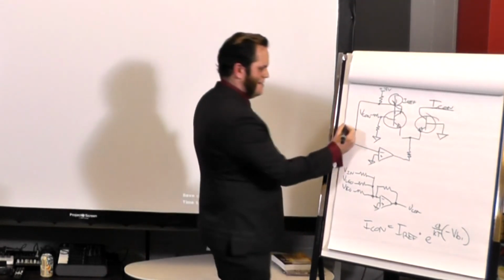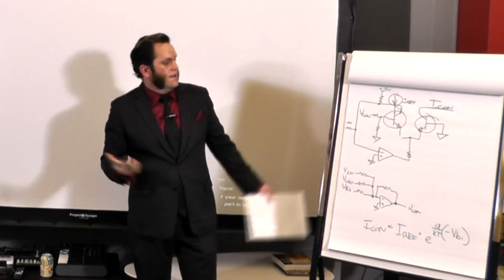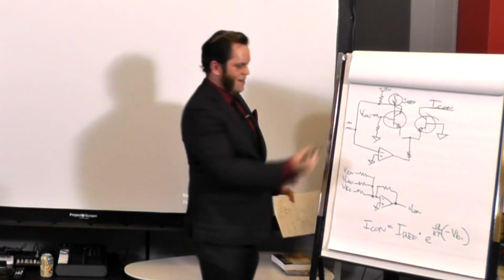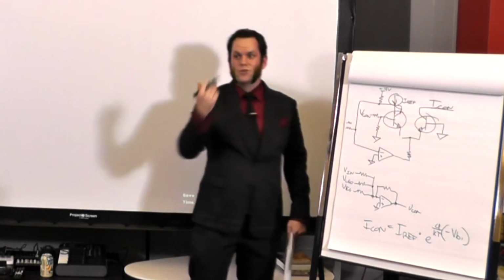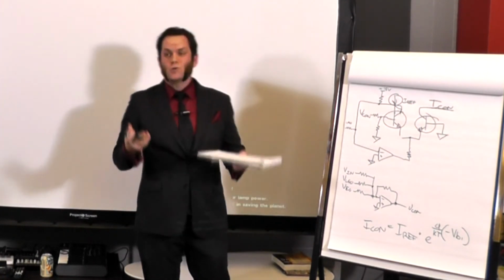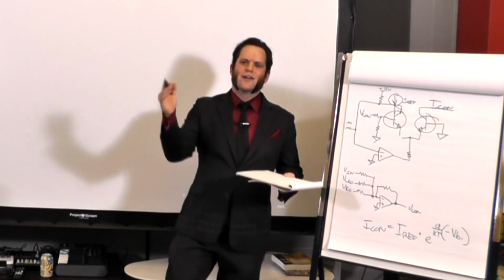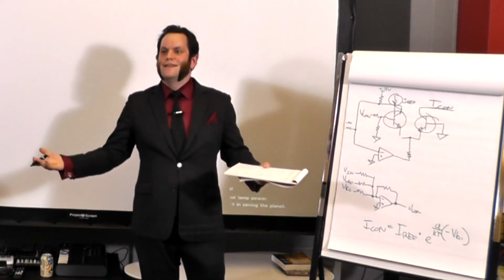So if I want a linear LFO to wobble my frequency, I can just throw that in there, and now I'm getting linear current changes for linear voltage ins. Depending on how you wire this guy up, you can get all sorts of fun control signals into the current going into your OTA, doing that crazy thing with a filter. Isn't that super neat?